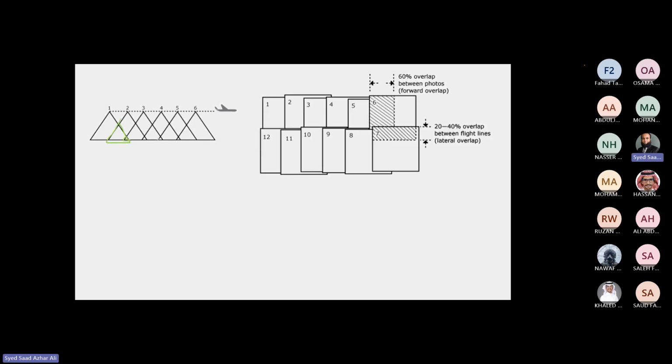Okay, so assuming that this is the UAV flying at 1, 2, 3, 4, 5, 6 waypoints, and at each waypoint it is taking an image. You can see when it is taking at 2, it is overlapping. This much is overlapping. Even the third one is overlapping with the first one as well. So there's an overlap. Okay, and this overlap results in images like this. If you notice that each image is quite this much, so this means one can go all the way probably here and all the way something like this. So going forward, it is having an overlap by 2 and 3 as well.